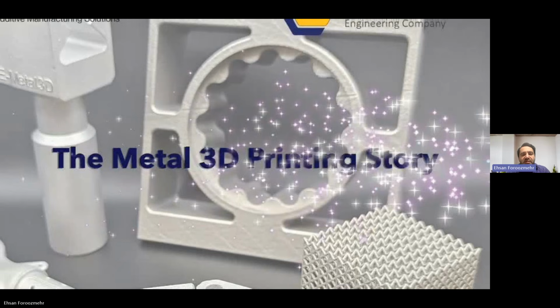That side goes down 60 microns, and the other side, on the right, comes up by about the same value, and the coater goes to the right and brings back the powder on the left side. Then the next layer starts and the laser starts to melt. This process continues thousands of times until the whole part is done.